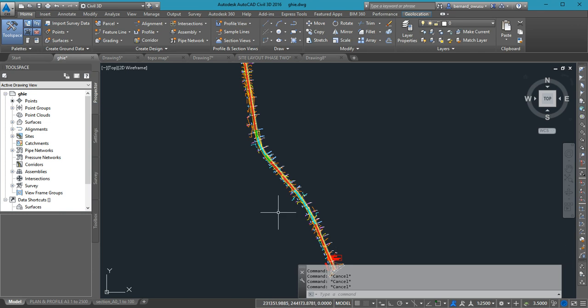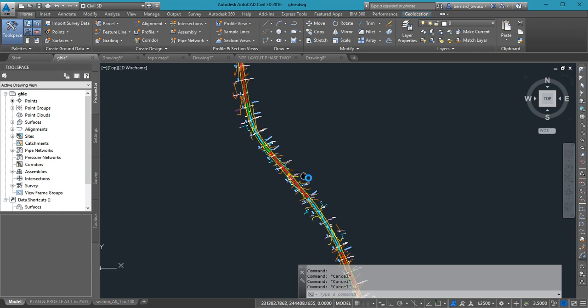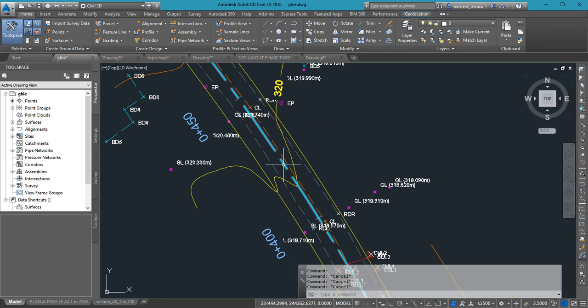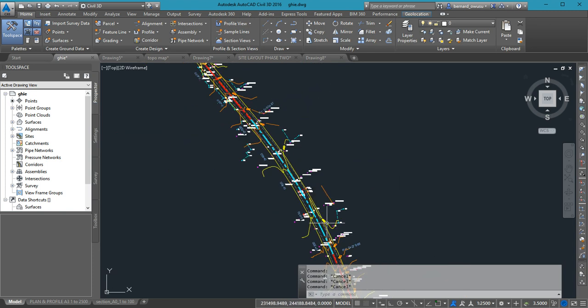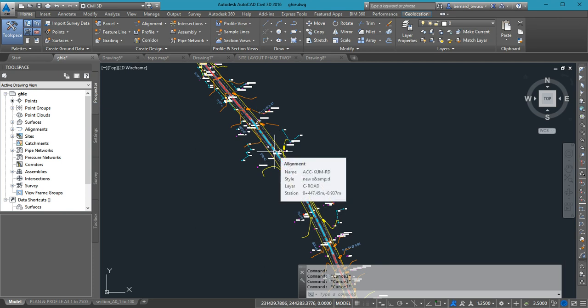Do you understand? Also, if you have a warning on a curve, it means that if it's on a curve, the arc, either your radius is below the minimum or the length is also below the minimum length. The minimum length, you can get it from the design guide. What minimum length for a design speed of say 60 should be.